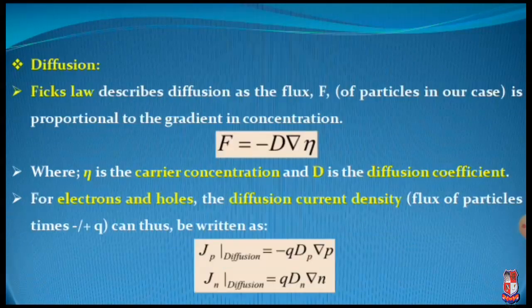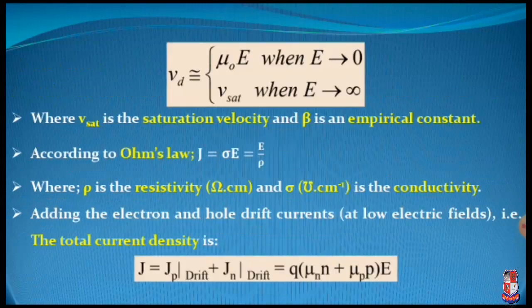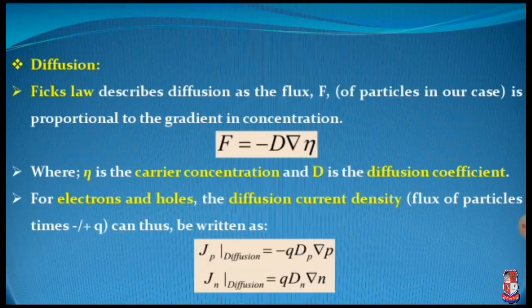Now we will see the case of diffusion. In order to consider diffusion, we have to study Fick's law. Fick's law describes diffusion as the flux of particles, in our case, being proportional to the gradient in concentration. So F is equal to minus D into gradient of N, where N is the carrier concentration and capital D is the diffusion coefficient.